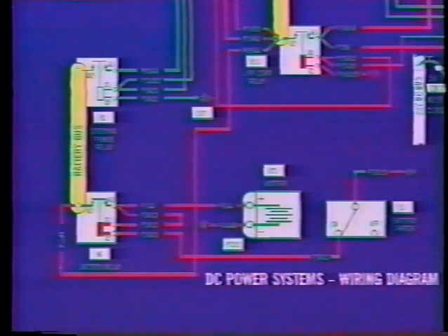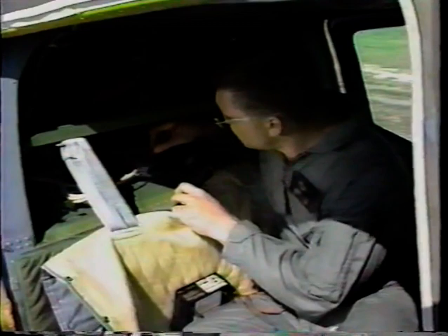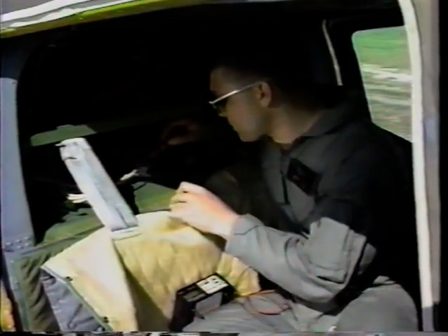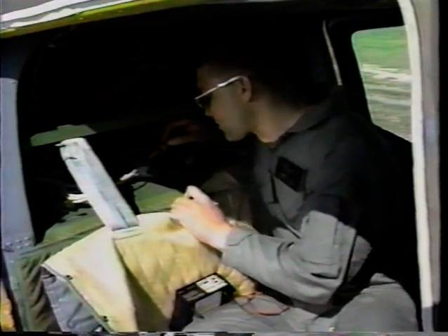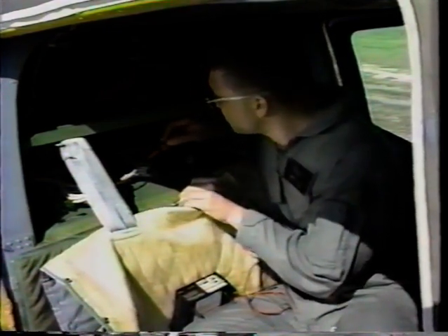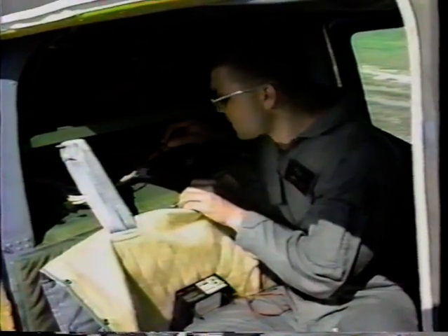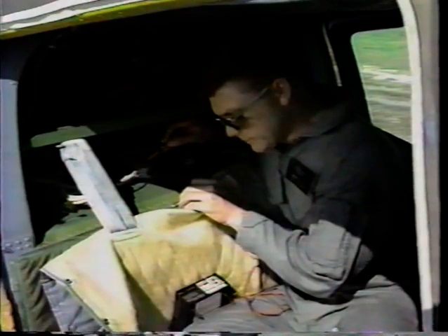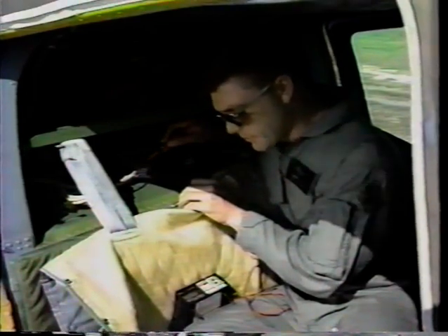The generator voltage output must exceed the battery voltage output by 0.30 to 0.42 volts before any of the preceding can happen. The question must then be asked, what happens if the voltage output of the generator is weaker than the battery voltage? This is most often the case when the voltage regulator is incorrectly adjusted or malfunctioning. Let's look at the case of a poorly adjusted voltage regulator.